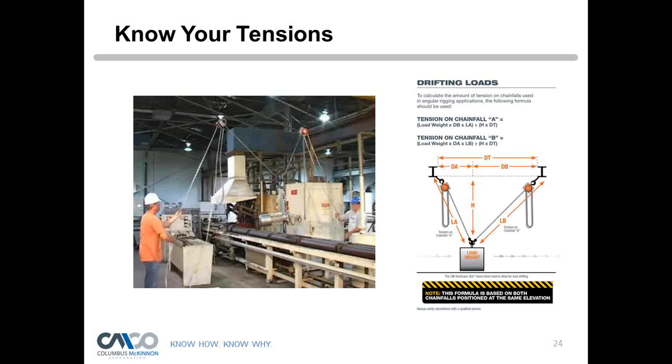Okay, and for this presentation, we're only showing that because it gets a little bit more complicated when you have off-level pick points, and it just changes the tensions up a little bit. So if you have that, seek a qualified rigger to look at that for you. And really, it is the qualified rigger that should be performing these operations. What we're showing here today is more of advanced rigging. So basic rigging training really is not good enough in these instances. Someone needs some advanced rigging knowledge to understand how they need to accomplish these types of lifts and calculate tensions.